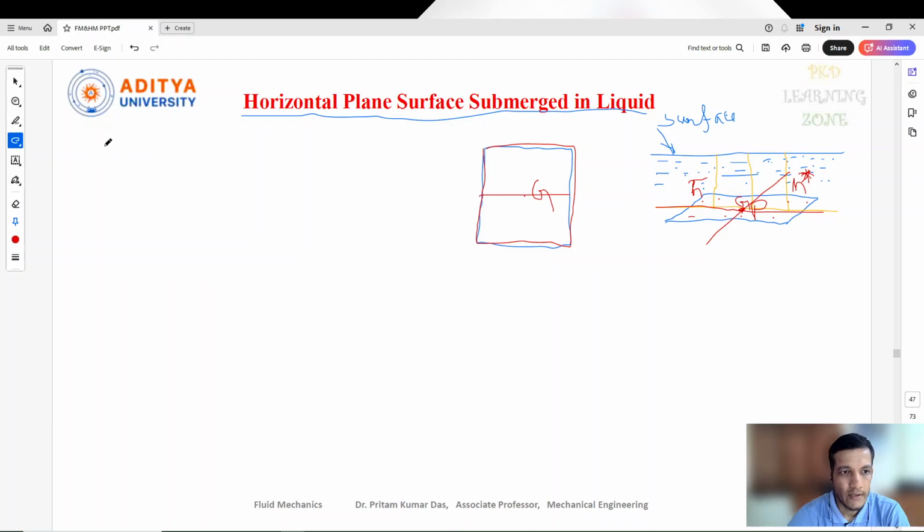So we know that the pressure which is acting here on the surface can be written as P equal to rho gh. This formula you have already derived in the previous lectures. And the area is the cross-sectional area of this plane surface. While calculating the pressure force, we know that pressure is also equal to force by area.